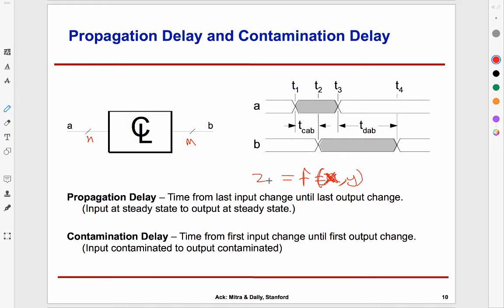So it's almost like there is an entity sitting there monitoring the inputs, and whenever any input changes, it recomputes the output immediately. You can think of combinational logic in that way. It's a hardware program, whatever way you might want to think about it. What it is doing is continually monitoring x and y at all times. And whenever x changes or whenever y changes, it recomputes f and dumps it on the output. So in Verilog, we accomplished that by making the sensitivity list of the always block include everything. So combinational logic you can view in that fashion.